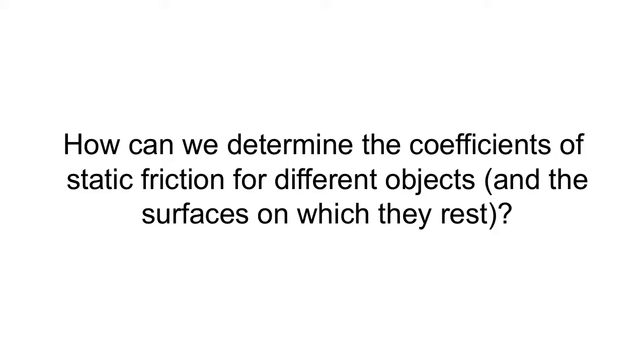And the way I do it in this problem that's most efficient, I want to understand this static coefficient of friction. I want to ask, how is it quantified in this problem? It's basically the weight times sine of theta, this comes from the first equation, divided by the magnitude of the normal force, it's this piece. And I know from the second equation that that N is equal to weight cosine theta. So I get this expression, weight sine theta over weight cosine theta.